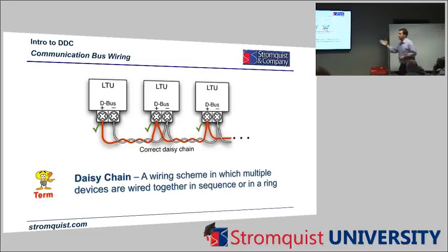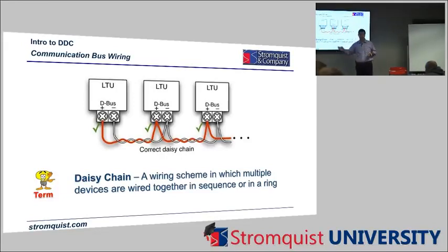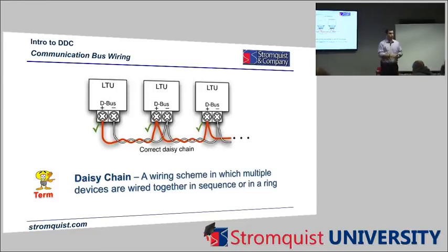But the reason that we do that, does anybody want to take a guess? Why would we daisy chain this stuff together? Parallel, okay, yep. What else? What happens in a daisy chain if this controller goes bad? Think about the wiring. Remember what I said? We twisted those wires together before we stuck them into that terminal. So if that middle controller goes bad, you can still read the rest, you can still read everything else, right? So we're going to get something on our graphical page that says this controller is bad, but it doesn't kill everything else downstream. You know your Christmas lights, they're a little different now, but when one bulb goes bad, the rest of them don't work?